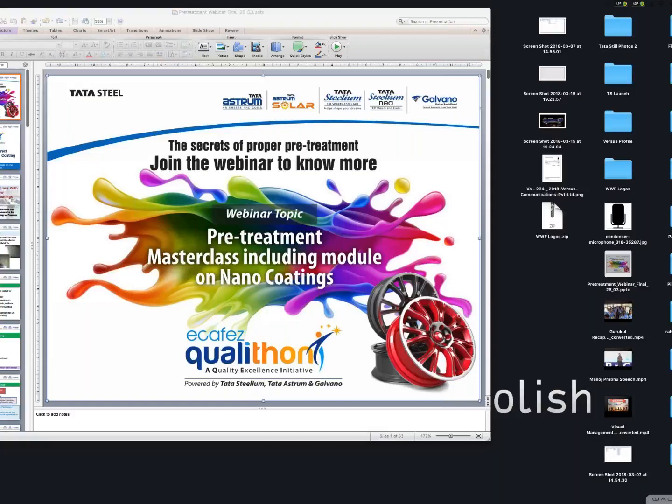Again, Mr. Rawat is saying in the de-rusting stage, many applicators use commercial HCl. What effect will this have on the coating performance? Now, this particular HCl, or any other strong acid, if by chance it goes into the gaps or the cracks in your fabricated jobs, like between two sheets, and it remains inside, the corrosion will be much faster.